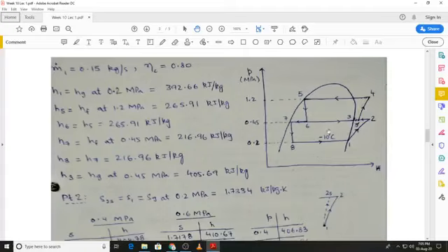You have the vapor at state 4 entering the condenser. It is condensed to saturated liquid state, then it is throttled to the intermediate pressure of the flash tank, where the liquid is separated at state 7 and the vapor separates at state 3 over here.